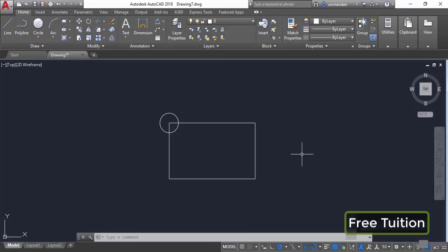In this video, I will tell you about move and copy tools of AutoCAD. So here we have this rectangle and we have a circle here on one of the vertices. Now let's say that we want to move this circle on the second vertex here. So for that, we can select the move tool from the modify panel. So select the move tool. Now click on the circle, press enter, and now specify the base point.